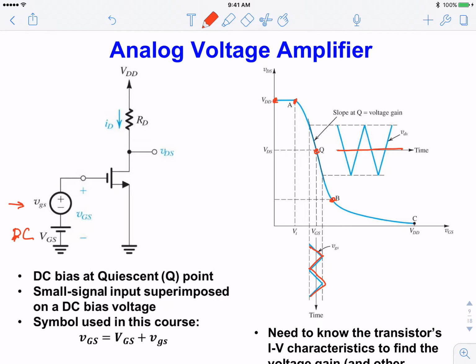So basically, the gain is like the slope of this curve, because this is the transfer curve. This is output versus input. So the gain is basically the slope. So slope will be equal to the gain. Okay, and the slope is negative, meaning this is an inverting amplifier. It is an AC. When your input voltage decreases, your output voltage actually increases. So they are 180 degrees out of phase.